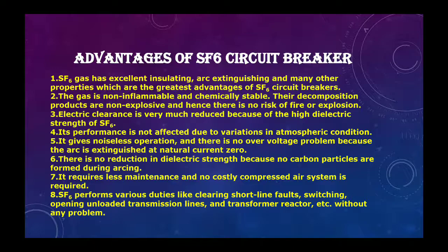And the last one is SF6 performs various duties like clearing short line faults, switching, opening unloaded transmission lines, and transformers, reactors, etc. without any problem. So these are the advantages of the SF6 circuit breaker.